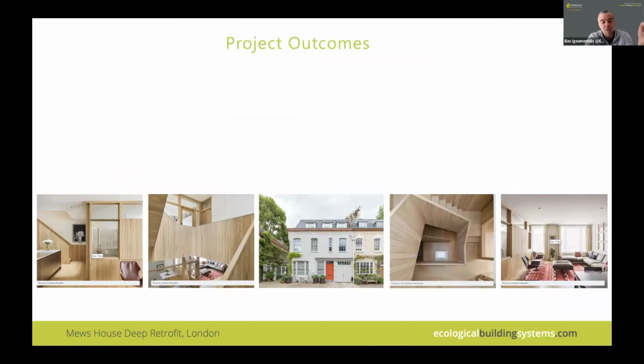The space heating demands reduced from 240 down to 40, which is much better than even the criteria for constrained properties, which is 60. And the switch from the gas boiler to air source heat pump was much more efficient. So the efficiency went from 90% to 360%. So that's significant. So all this, the combination led to a major reduction of operational cost, carbon emissions from 65 down to, I think it was 12. So yeah, 4 or 5 times better.